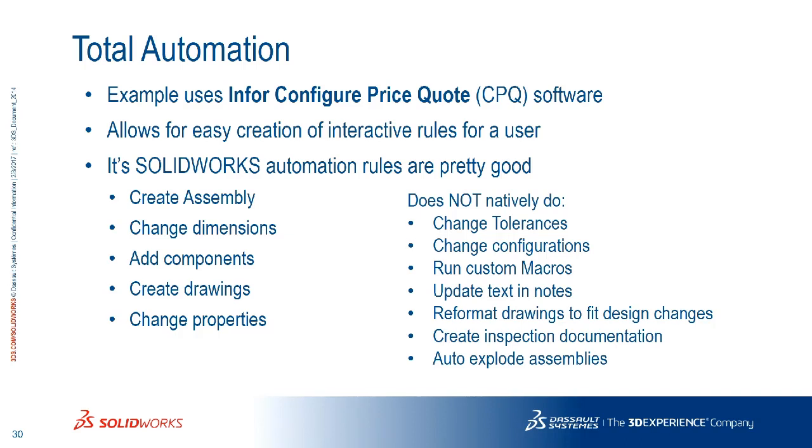All right, so the question was, how am I referencing the particular dimensions and things like that? Every dimension and pretty much anything that you click on inside of SOLIDWORKS that'll highlight has a unique name associated with it. If you're working within a part or within an assembly, you can actually change that name. If you're inside a drawing, it doesn't natively come up to say, hey, you can change this from being D1 to be D2. That was another program that I wrote that I didn't show here. I can click on any dimension in a drawing, and I can pull up what the name of it is and override it to make it something as opposed to being detail item number 563, because that makes no sense to me. I can call it finish bore or rough bore or something like that,